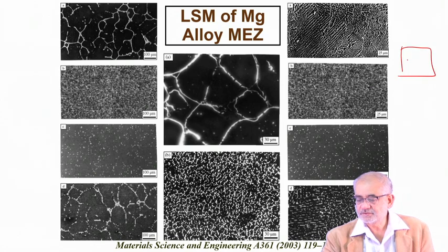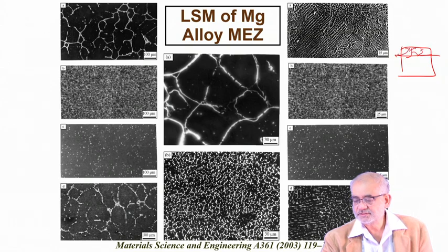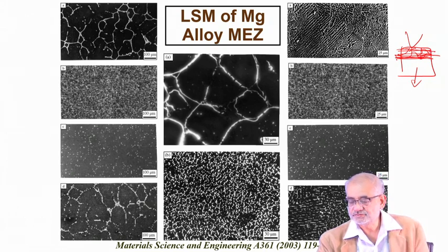So if this is a bulk component and we are melting this surface, so if we have, let's say, such coarse microstructure, then we can convert this by surface melting. We use a laser beam, we raster over the surface and allow melting up to a certain depth, and then rapid solidification, because this is a solid-liquid interface, the maximum depth the solid-liquid interface moves down to.